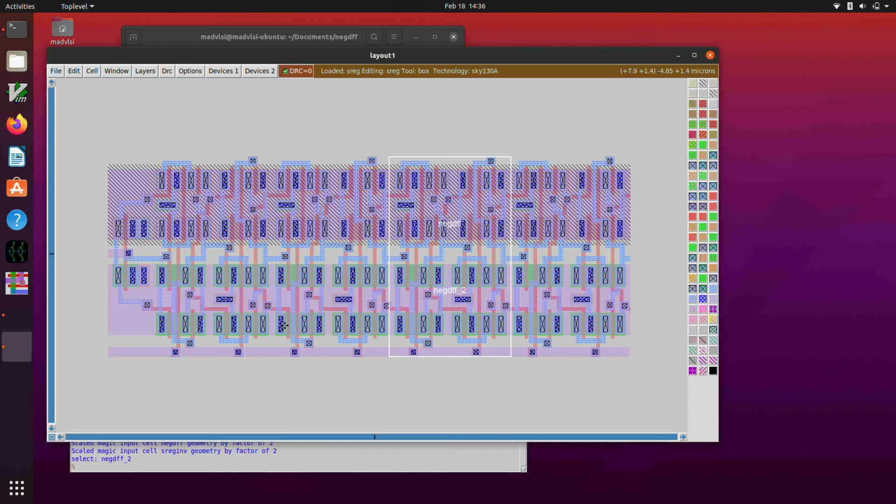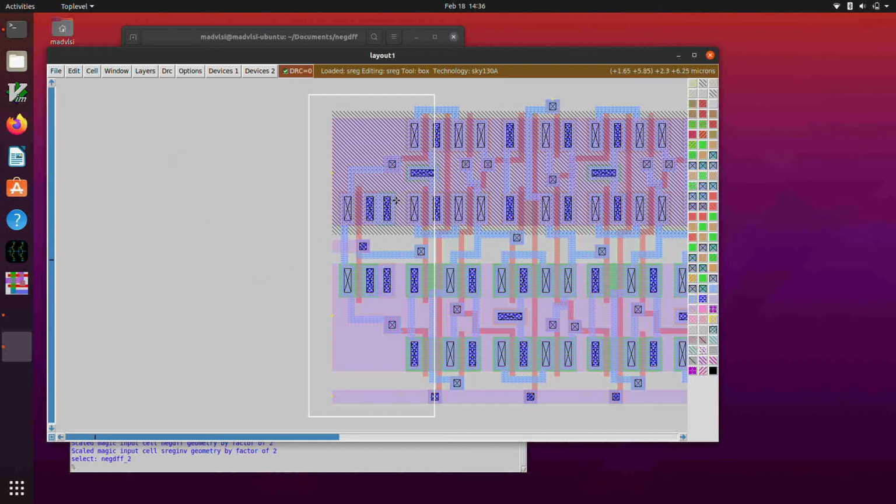But the other thing which I've done here is I've designed an inverter cell to generate D bar from D. If you remember how this negative D flip-flop cell works, the 2 D bar inputs come in on poly on the left-hand edge of the cell, at the bottom and the top, and the actual connection between them is made in the right-hand side of the cell that's to its left, right?